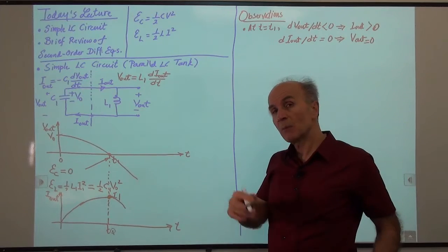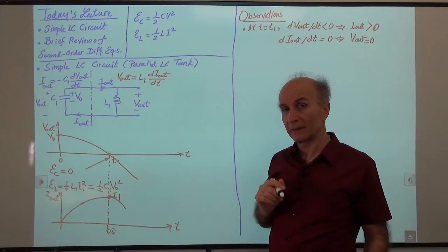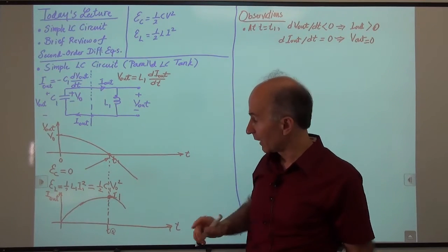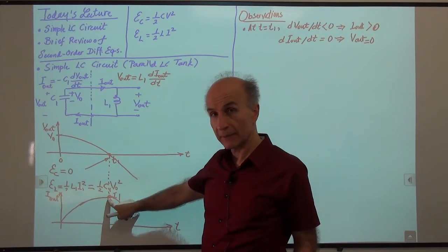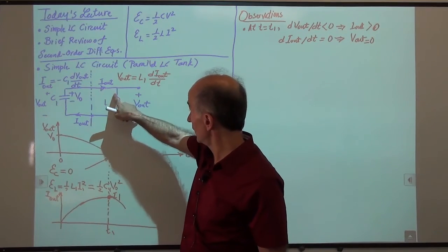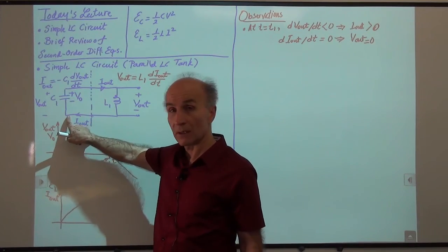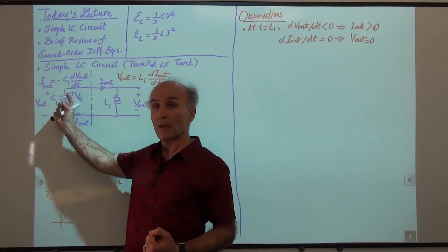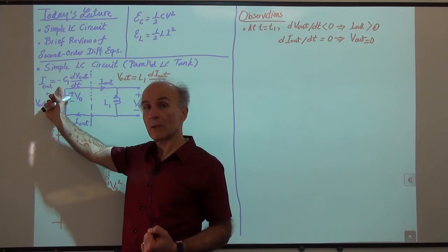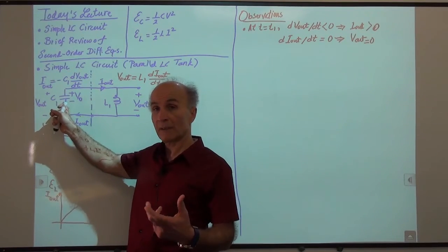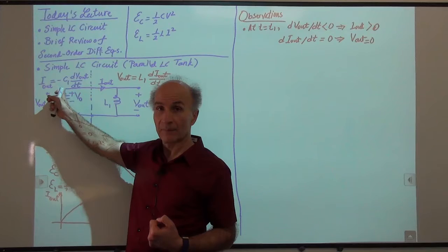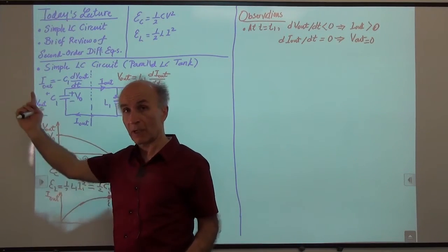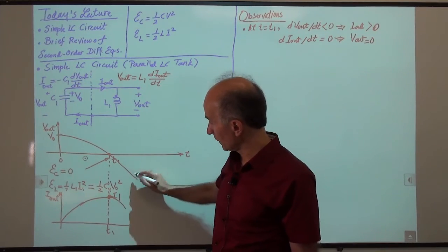Why is the voltage becoming more negative, not more positive? Well, let's keep track of the current and its direction. I out is positive, right? Where is I out? I out is here, I out is here, I out is here. So I out is positive 1 milliamp, and it's going in this direction. If you push current in this direction to a capacitor, this side will be more and more positive, this side will be more and more negative. So V out will be more and more negative because we're pushing current from the bottom, right? So then the voltage becomes negative.